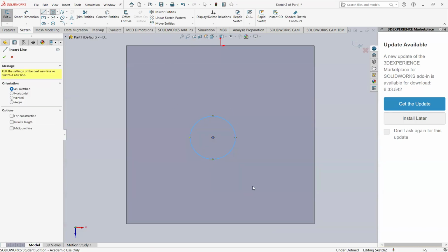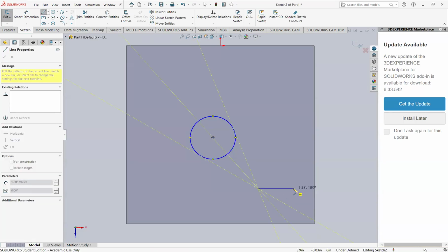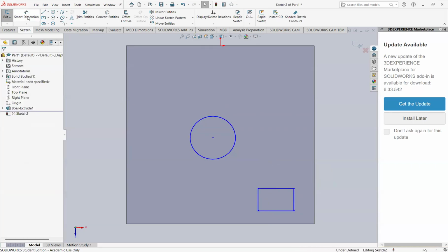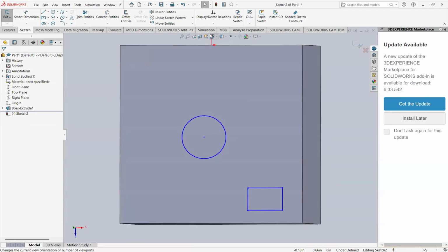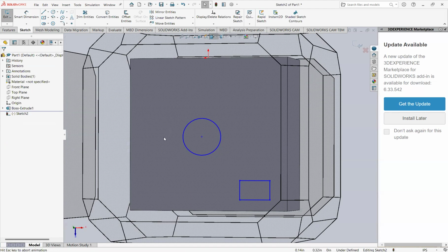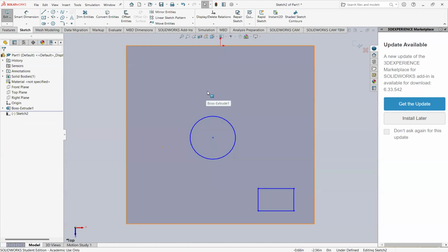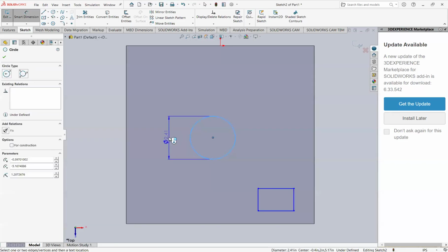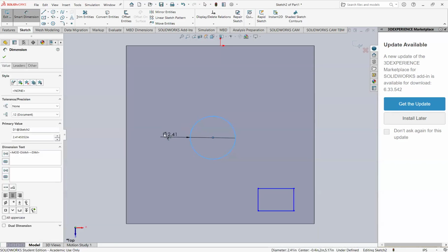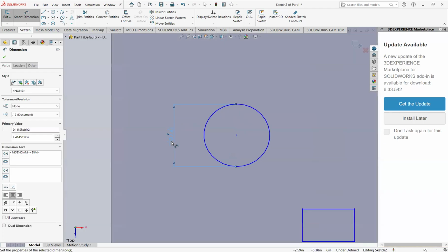We'll also do some other lines, because it's important to learn some of the other ways to define things. So here, make a box. You could have used rectangle, but I just felt like sketching it. Since we already defined this box, we don't necessarily have to define it to the origin. We can just define it with the box, because the box itself is defined. So we'll smart dimension. If you draw a circle, you'll see a symbol here. Let's just hit check. Awesome.